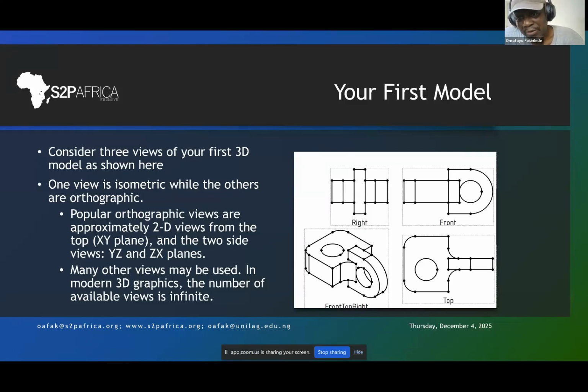But this is just another one, which is using the old engineering drawing perspective where you can take 3 views for the workshop. But now you can take as many views as you want. There is no need to restrict yourself to 3 views, but this is possible in the TechDraw workbench. One view is isometric while the others are orthographic. Isometric tries to make a 3D drawing in 2 dimensions still in such a way that the distances are preserved. That is what you call the isometric view.